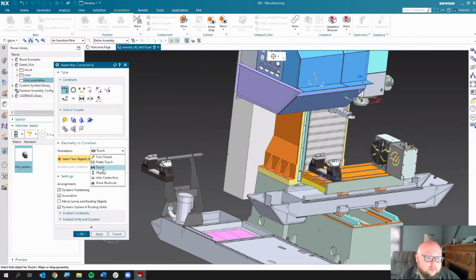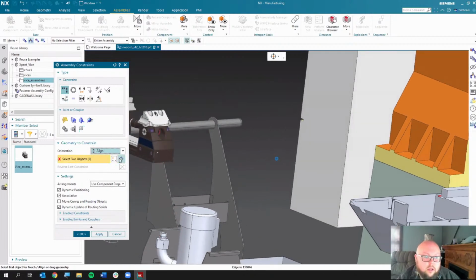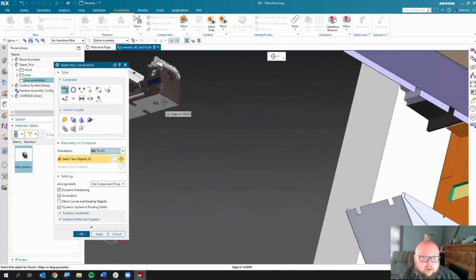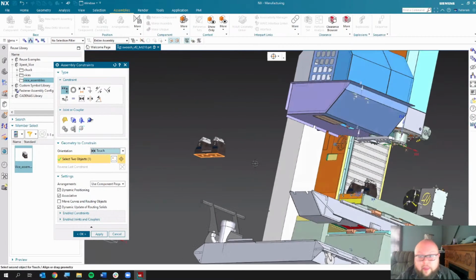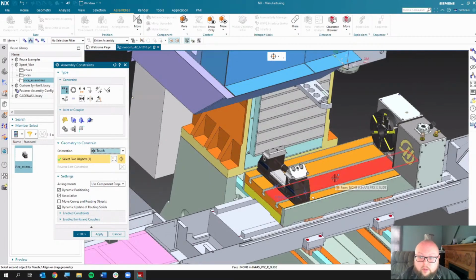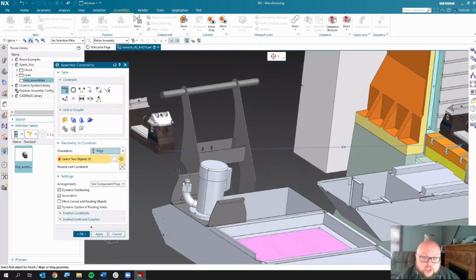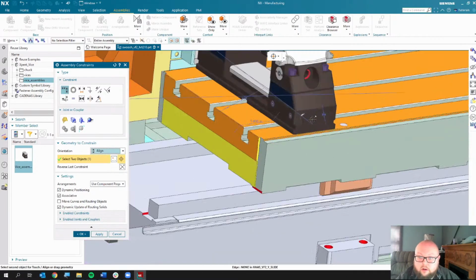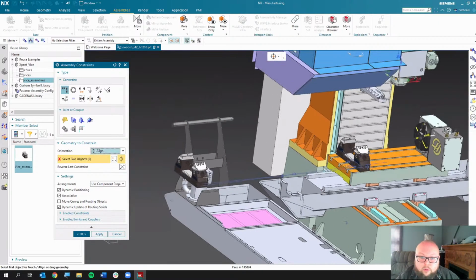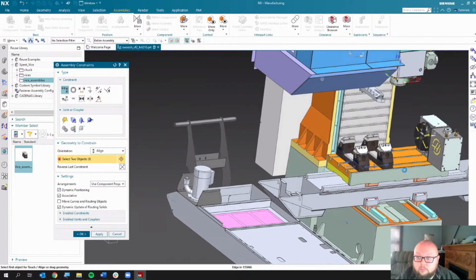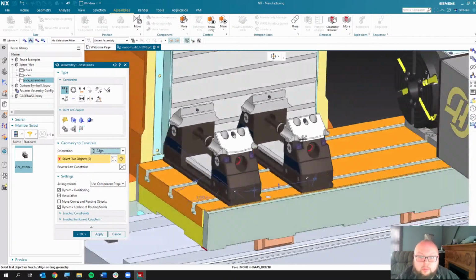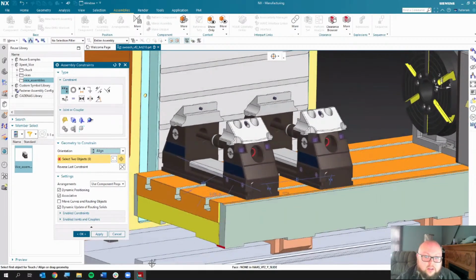If you haven't played around with that or started experimenting, it's a great way, particularly for us on the CAM side, to handle things like fixturing, clamps, hold downs, any kind of riser blocks for holding your parts. You want to check all the clearances to all this information. It's a very easy method for loading and reusing that data, as opposed to loading them as components every time and rebuilding assemblies. You can see I have my vise assembly set up here with typical jaws that I'll use.